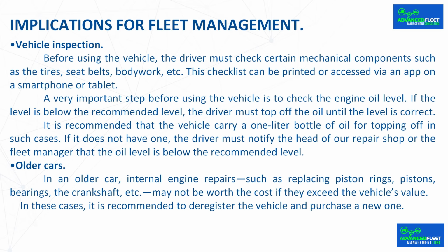Vehicle inspection. Before using the vehicle, the driver must check certain mechanical components such as the tires, seat belts, bodywork, etc. This checklist can be printed or accessed via an app on a smartphone or tablet. A very important step before using the vehicle is to check the engine oil level. If the level is below the recommended level, the driver must top off the oil until the level is correct. It is recommended that the vehicle carry a 1-liter bottle of oil for topping off in such cases. If it does not have one, the driver must notify the head of our repair shop or the fleet manager that the oil level is below the recommended level.